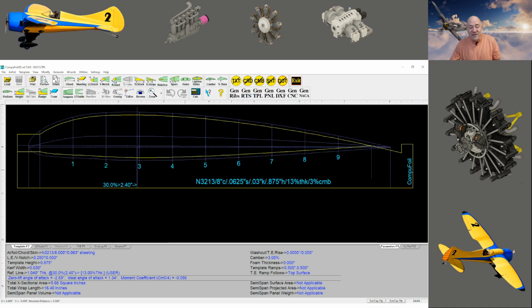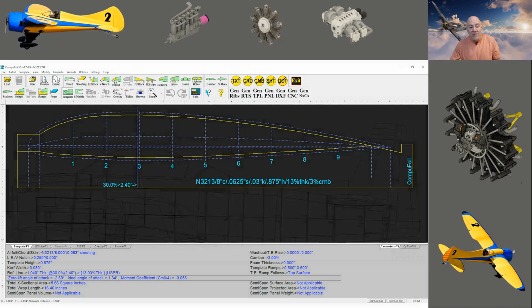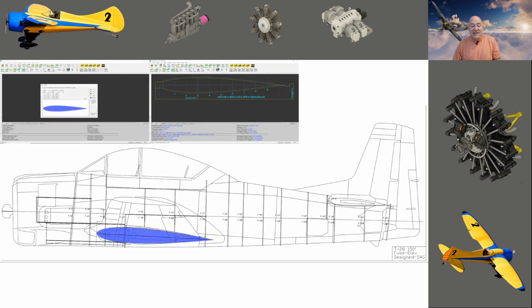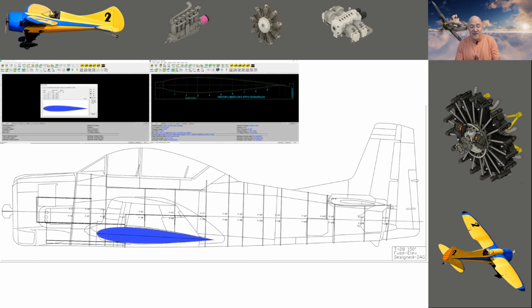That's what it would look like if I was to plot it out. I was going to cut it out. But here's what I want to show you, something that's interesting. This is the big 150H T28 I'm designing. And I decided to use a fully symmetrical airfoil, but I'm going to put a pretty high, about 3¼ degree incidence on it, so it will look like this.